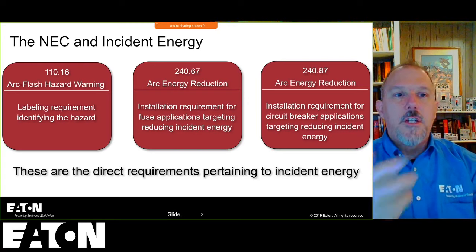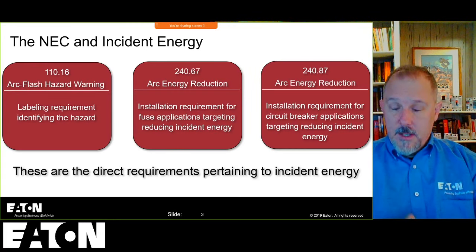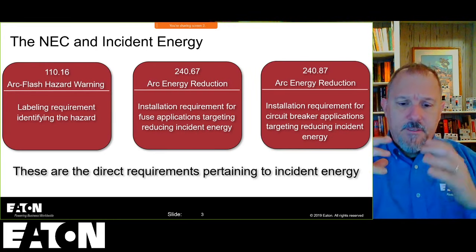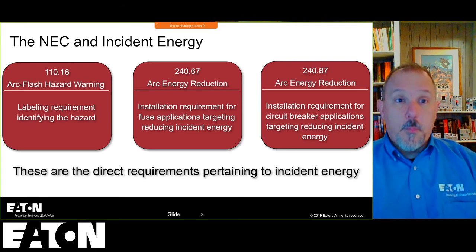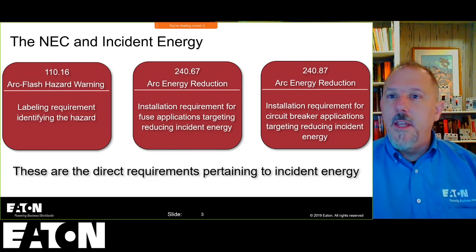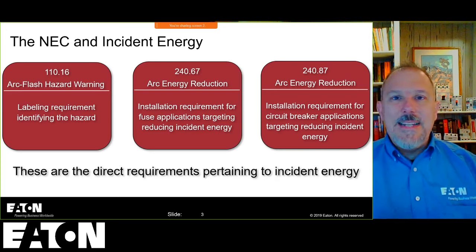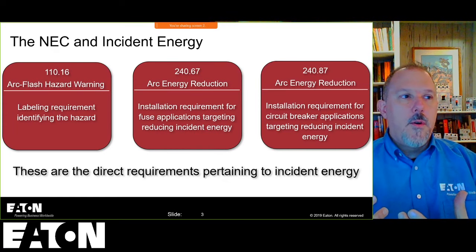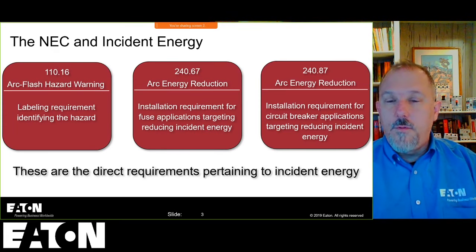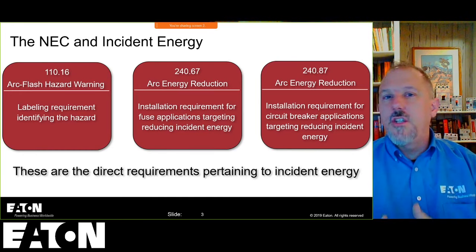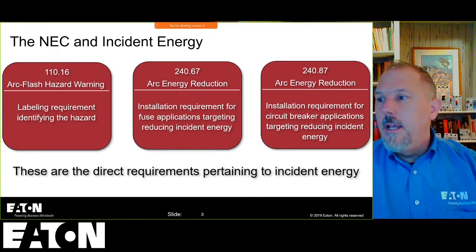We had this discussion a couple days ago. On the ungrounded system, all your motors and everything were delta configurations. They didn't need that grounded conductor in the system, because electricity was initially used for industrial applications, for rotating motors and things like that.